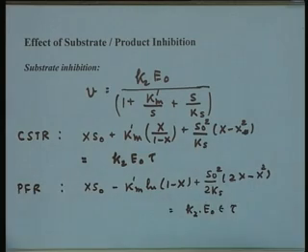You can just use these two equations and substitute arbitrary values for fractional conversion at a given substrate concentration. The performance of CSTR works out to be far superior compared to a plug flow reactor, because the substrate concentration at any given time is physically much lower than in the case of PFR, where for the bulk part, more than half, the substrate concentration is very high, and only in the upper half does the substrate concentration go down. In fact, the reaction rate varies in the PFR along the length of the reactor.